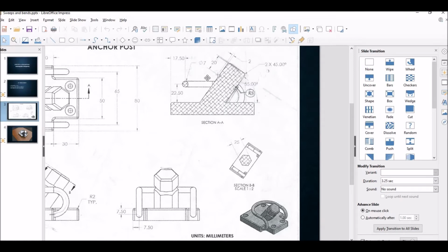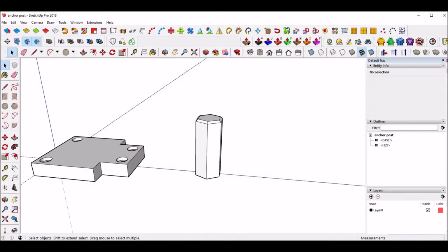Well, first off, if you think about it, it shows a positioning right here of 2 millimeters out for that radius of 3. So it looks like we're going to have a circle that's going to perform an actual tiny little circle like a coin. Think of a coin, and that coin is going to spin around, and it's really sharp, and it's just cutting away this. So how do we do that? We're actually going to make a continuous, like a coin in an infinite amount of circles, so basically a ring.